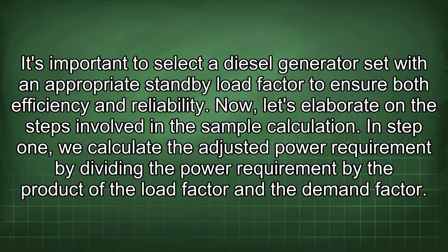Now let's elaborate on the steps involved in the sample calculation. In step 1, we calculate the adjusted power requirement by dividing the power requirement by the product of the load factor and the demand factor.